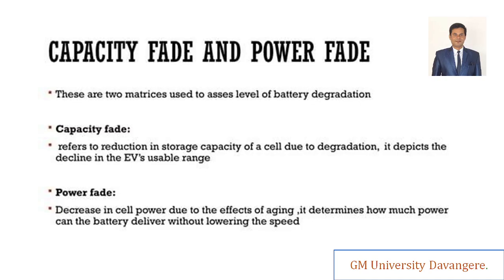The reasons are very specific, right? Sometimes the internal resistance rises, and the electrolytes may also decompose. That would be a reason sometimes, right? So we cannot say exactly why the degradation is happening in the cell, why it is not delivering the power. If you take the electrode in the batteries, what will happen in the electrode actually? The internal resistance of the electrode may increase, and it is not able to generate that much energy, due to the electrode cracking.